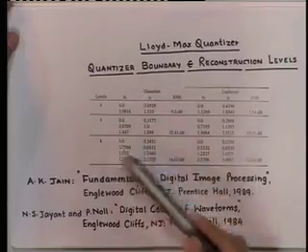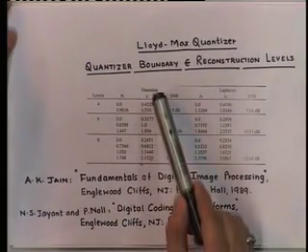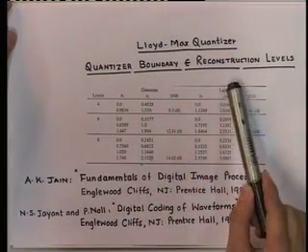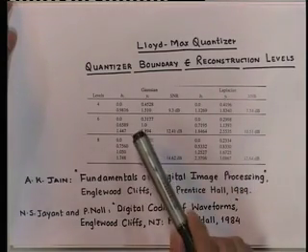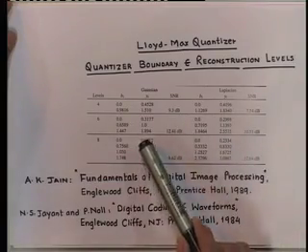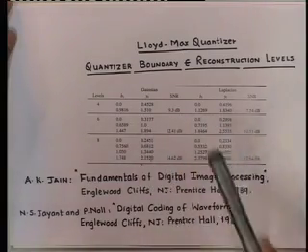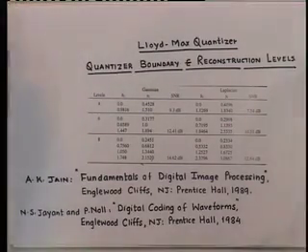For example, in this table which we saw earlier, the values were obtained under the assumption of either Gaussian PDF or Laplacian PDF, and it was also assumed that the input PDF has 0 mean and unit variance. But now, in a practical scenario, it is strictly not necessary that the actual input source behaves as the one assumed while designing the quantizer.